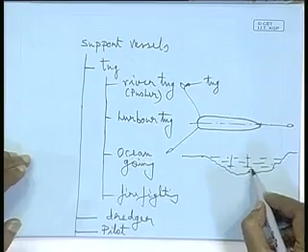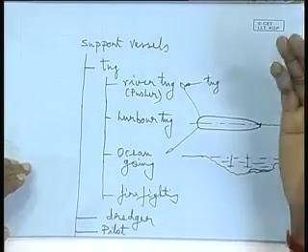Why is it so important? Do you have any idea why it is so important? Because if you do not do that, the vessel may get, what happened? May get grounded. The term used, grounded, means stuck in the silt. Stuck means it will suddenly sit on the silt. Suppose the draft is less, it goes and plows into the silt. So what's the problem? It's not only a question of coming out; it may tilt and capsize immediately. Why? That we will learn later.